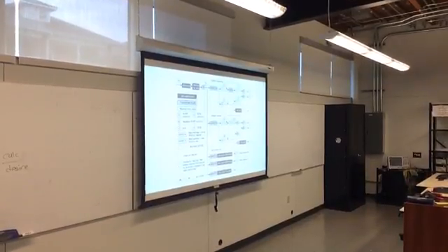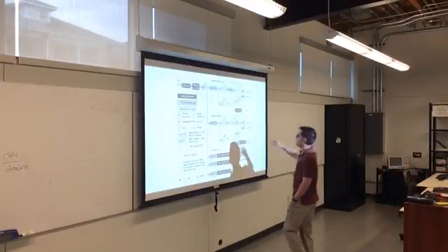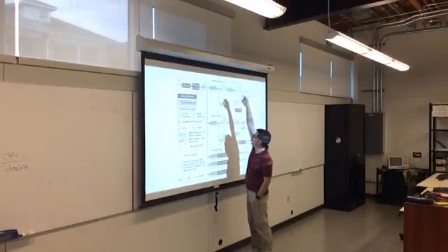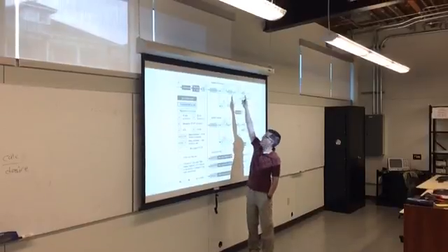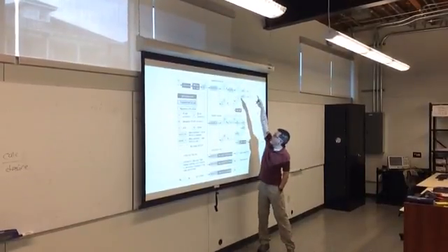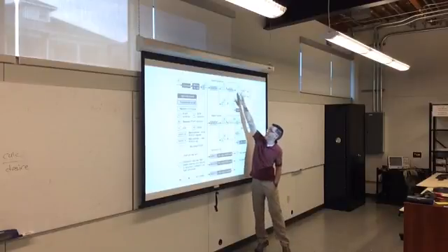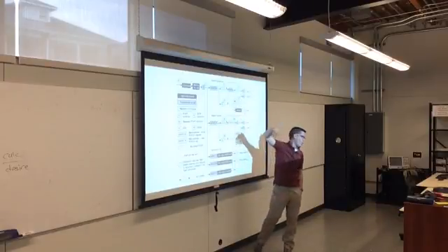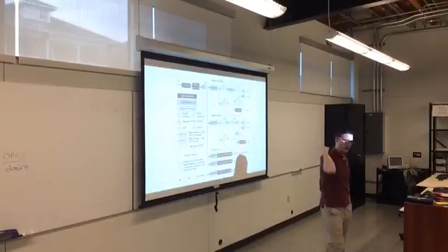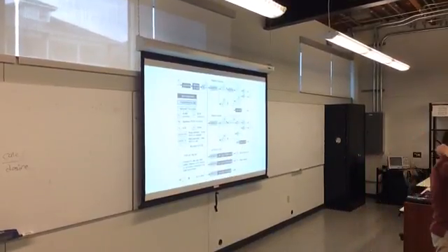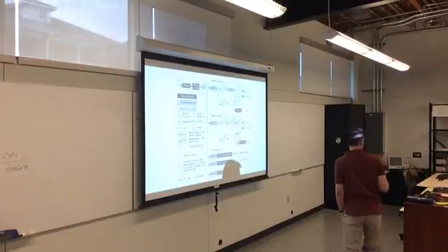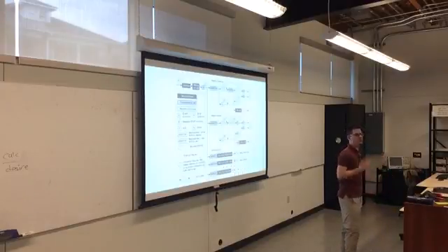Once you send the data, the slave device will acknowledge it, and you can keep going through this loop. You can keep sending data, acknowledge, data, acknowledge, on and on until you do one of two things. You either stop, which is P, meaning stop the bus, or SR, which is a repeated start. You send another start command, which means you are not releasing the bus, but you are starting a new transaction on the bus without giving it up.